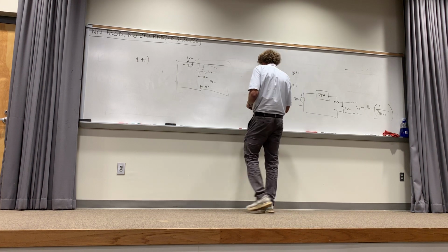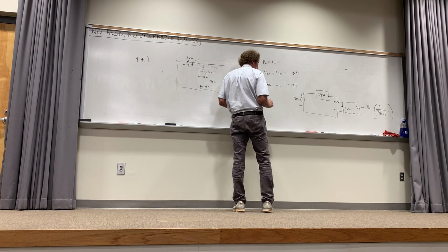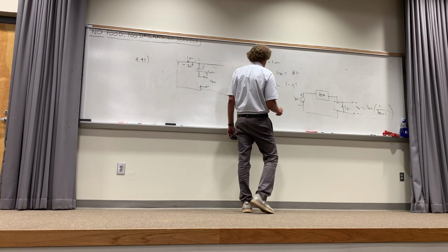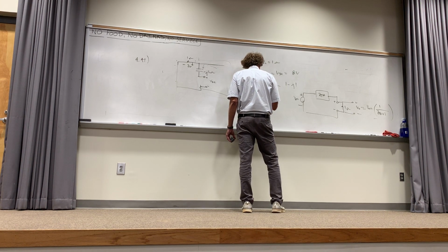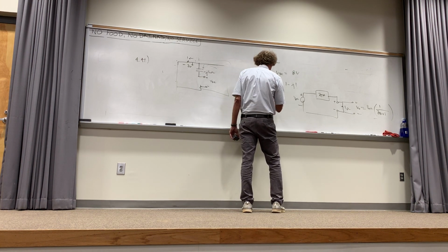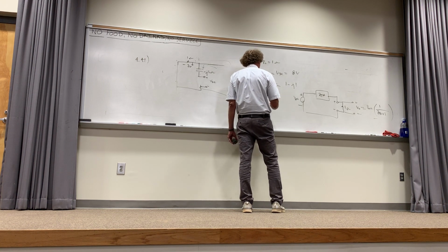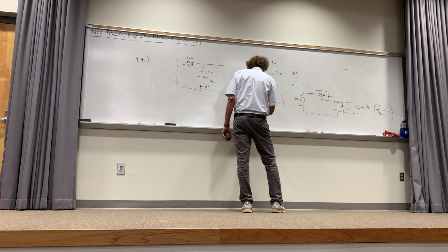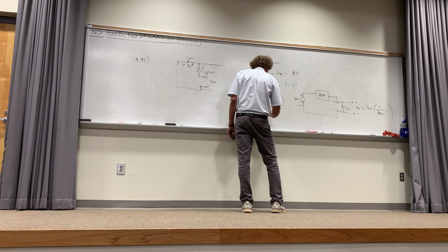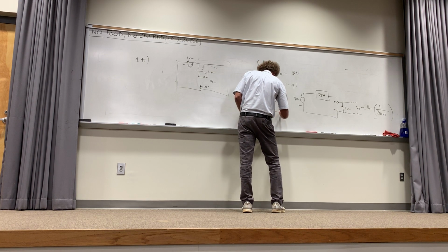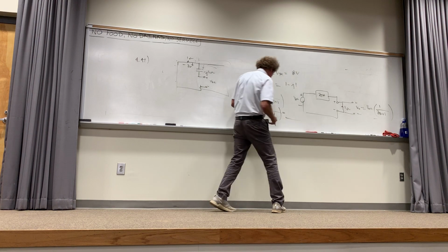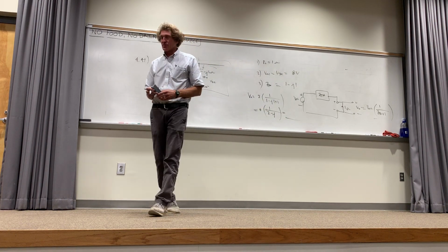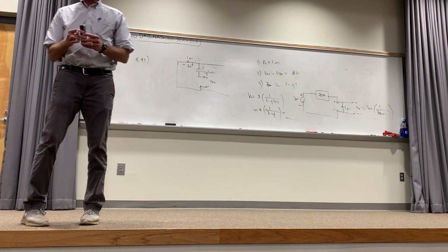That means that my V out will be equal to V open circuit, which is 8 volts, right? Then it's going to be times 1 over Z Thevenin, 1 minus J1 plus 1. You can see that's going to be 8 times, really, 1 over 2 minus J. And you can give that to me in polar. I might as well get used to using your calculators. Give it to me in terms of a polar number there.